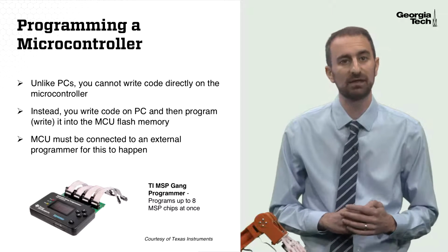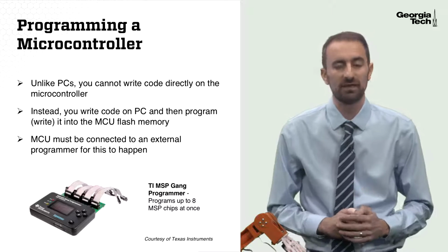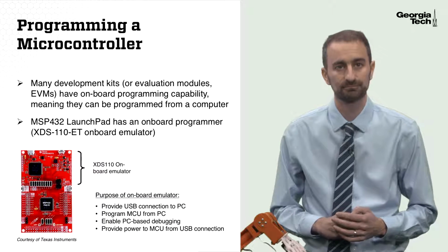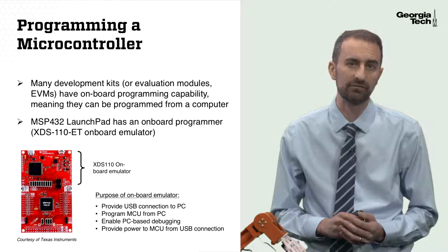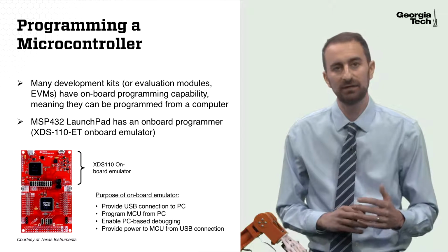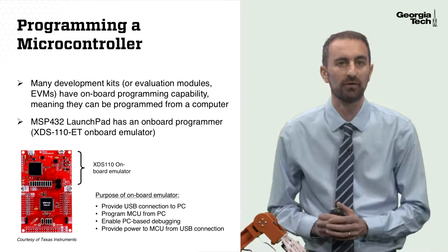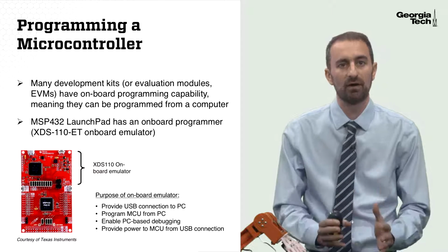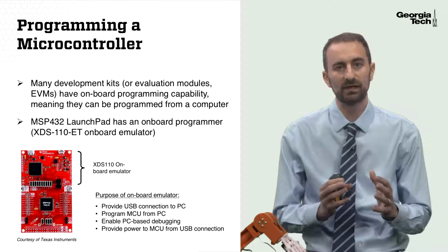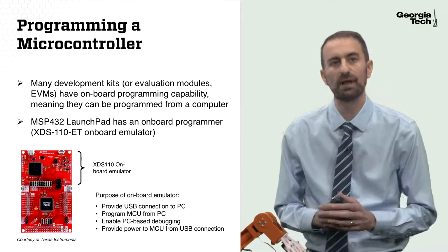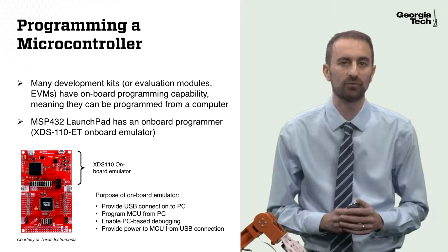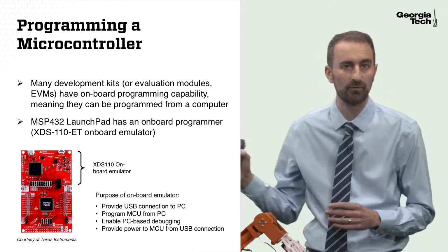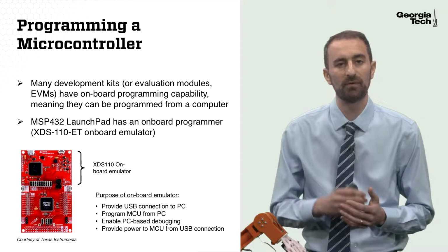Oftentimes these programmers can be expensive and are standalone devices that a typical prototyping operation doesn't necessarily have. The nice part about development kits or evaluation modules is typically you don't need this external programmer, but rather the microcontroller development kit has an onboard programmer on the actual device. So that means you can use this development kit and program it directly from a computer rather than needing that external programmer.